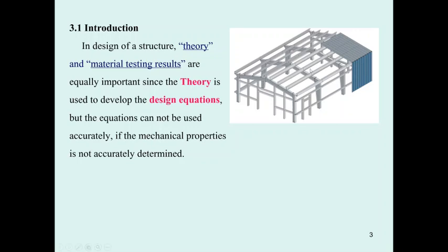The maximum deflection that occurs on the beam with uniformly distributed load is going to occur at the middle of the beam, and it's going to be Vmax equal to 5 times W, the size of the loading, times L, the length, to the power of 4, divided by 384 times E, the modulus of elasticity, and I, the moment of inertia.